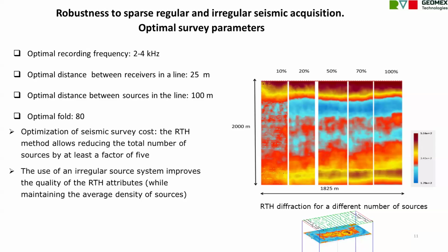Now you're talking about 2 to 4 kilohertz. So what is my sampling interval? Do we really do sampling that frequently? I'm not sure. Optimal means that it's very good to use for gigahertz, but we also used 2 milliseconds sampling. The 2 millisecond will correspond to 250 after Nyquist. So it'll be much less. 2 milliseconds is enough.